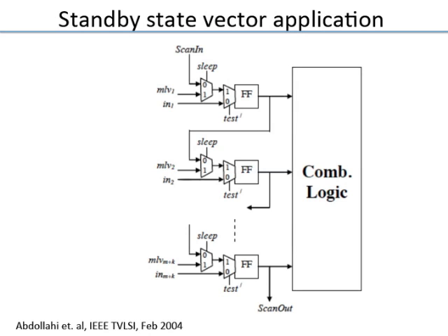You are making chips which have multi-million gates. Every gate has to work pretty much, otherwise the chip is dead. As a designer, you never think, what if that AND gate doesn't work? You just say, I'm going to add, multiply, and so on. You assume that everything is going to work perfectly, and remarkably, that is what is happening. The manufacturing industry guarantees that a sufficiently large number of chips work perfectly, and it is still economical. But to check that, people do what is called scan testing.